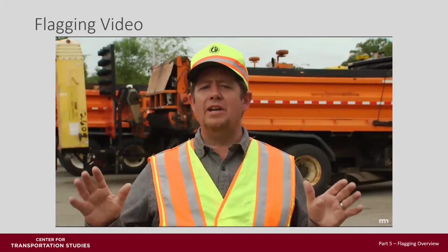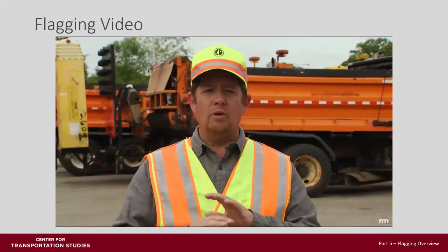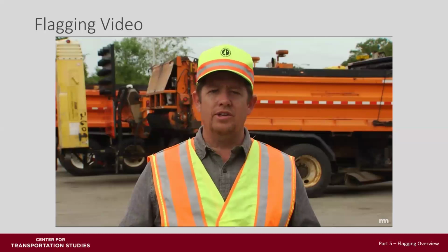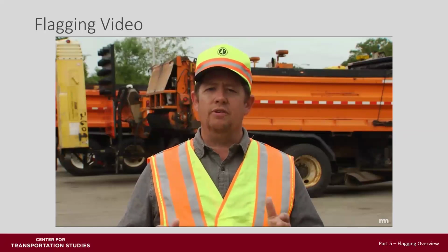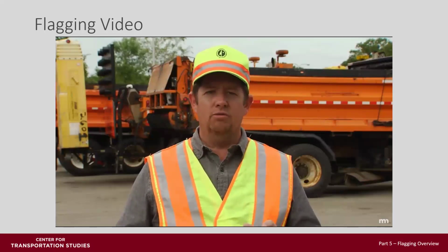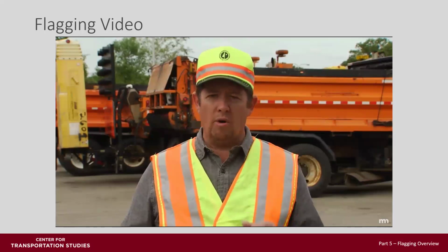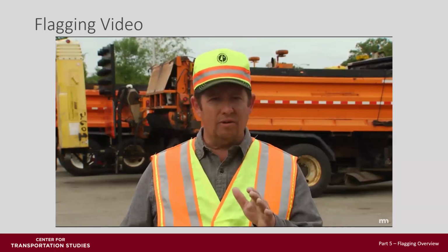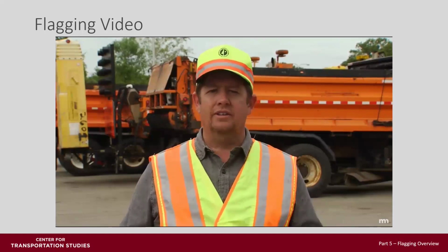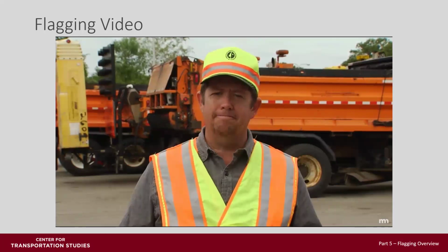If you learn these 3 basic skills, stop, release, and slow traffic, you'll be well prepared for any flagging operation. Situations will vary, and how you apply these skills will differ from project to project. Remember, never start any flagging operation without the proper equipment, stand in a highly visible and safe location, and never turn your back on approaching traffic. Now let's look at some typical situations a flagger may face.